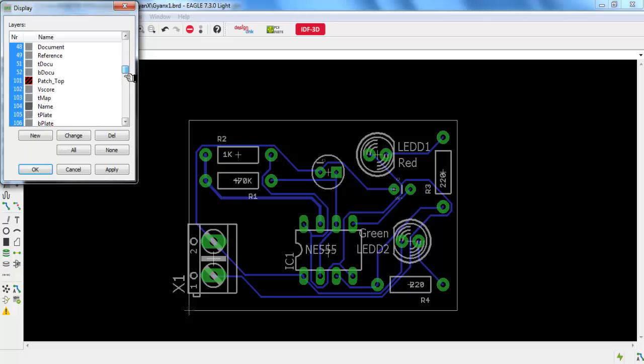So let's look at the layers that will be most definitely used before looking at some of the more exotic ones. When you add a part to a schematic, that part can contribute various things to different layers in Eagle. The package description will include such things as the size and the shape of the pads, and the names and the values that will end up on the pads and the names layers. This is the way you can switch to the board and see which layers are visible.